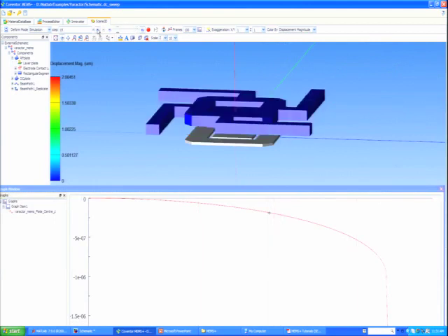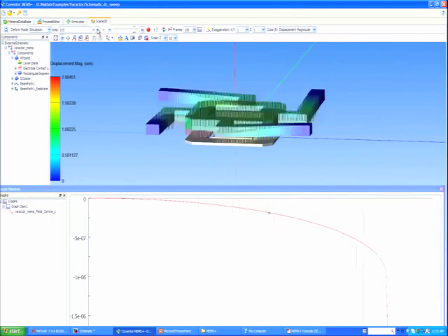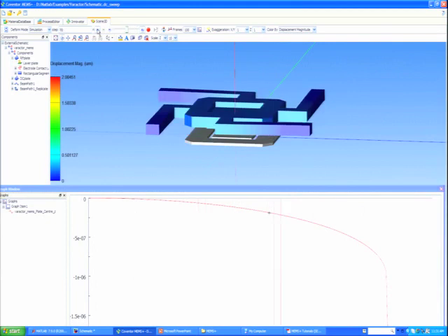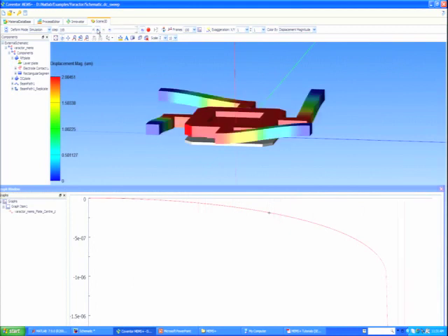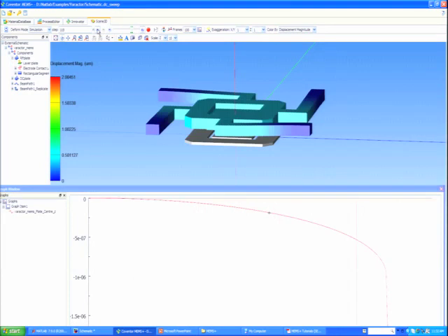What you should notice here is that we're simulating contact. We're simulating pull-in, which is an instability. We're running full electrostatics on this thing. Well, at this point, yeah, DC. So we have electrostatics on this thing. So all of this combined multi-physics we've got, and we know this is right because in the afternoon or after this, I'm going to run this in FEA and show you how well they match.